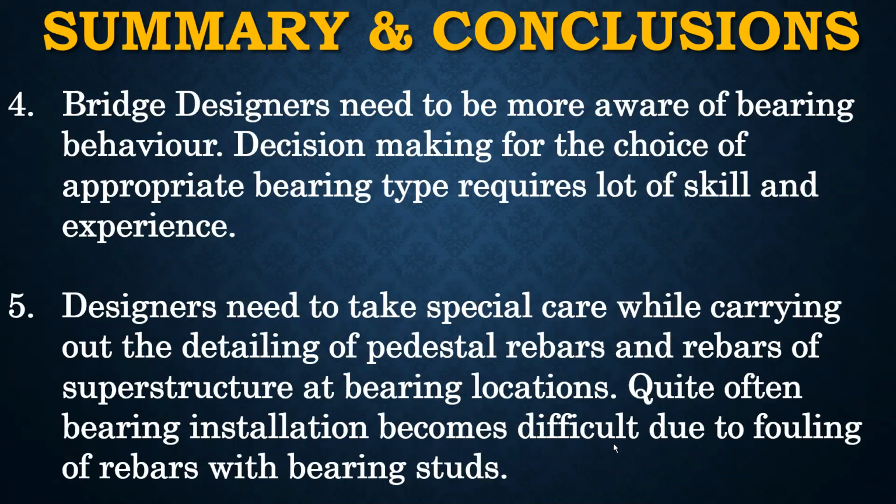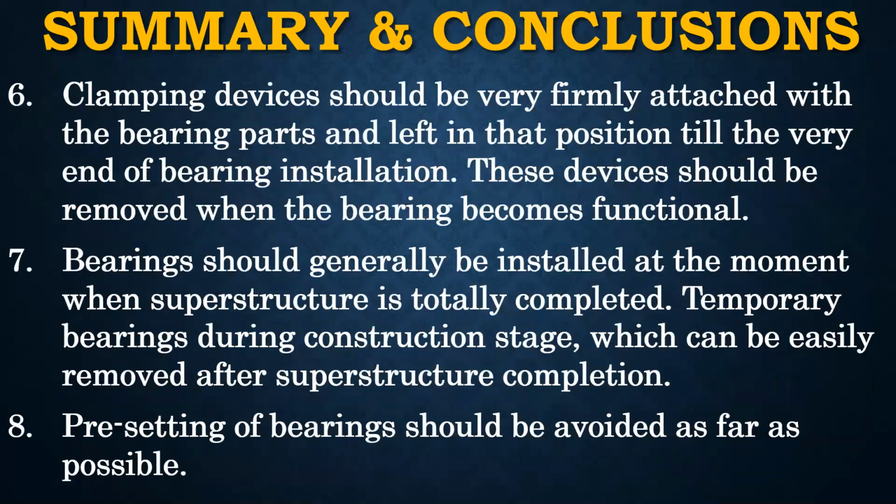Bridge designers need to be more aware of bearing behavior. Decision making for the choice of appropriate bearing type requires a lot of skill and experience. Designers need to take special care while carrying out the detailing of pedestal rebars and rebars of superstructure at bearing locations. Quite often, bearing installation becomes difficult due to fouling of rebars with the bearing studs. Clamping devices should be very firmly attached with the bearing parts and left in that position till the very end of the bearing installation. These devices should be removed when the bearing becomes functional.